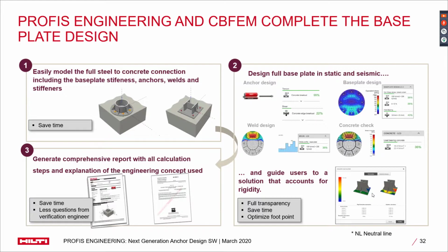The advanced baseplate module in Profis Engineering enables a holistic design of the anchors and baseplate as well as the verification of the actual stiffness of the material, which has a significant influence on the fastening capacity. Users can choose whether they want to do the design with the full advanced baseplate analysis considering the realistic stiffness of the baseplate or with the assumption of a rigid baseplate as done in the past by selecting the calculation process accordingly. The full advanced baseplate design is done with CBFEM procedure.